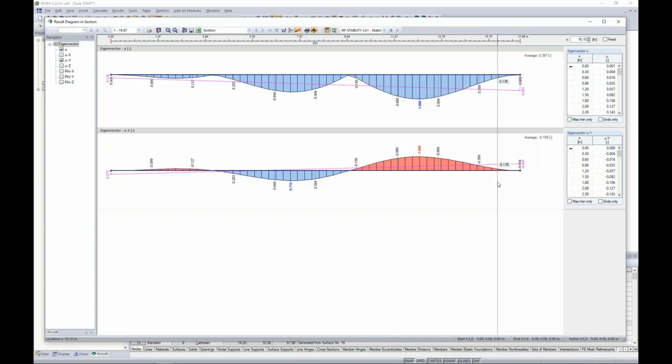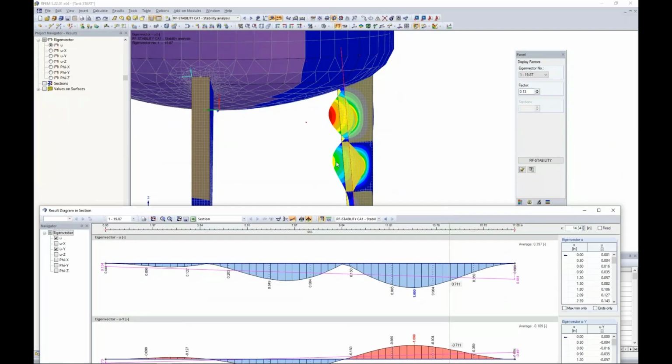We all know that when we are constructing a tank or any type of structure, there are installation errors, maybe incorrect construction methods, or we don't properly manufacture the elements, and inevitably we have imperfections. Everything that we are modeling within the RFEM program here is essentially perfect, and this is true for any general finite element analysis. All lines are perfectly straight, and all elements join together at every FE mesh point, when we know that in reality, lines probably won't be straight and surfaces aren't all in one plane. Mistakes happen, and there are tolerances given for these mistakes.